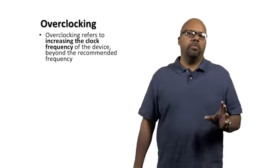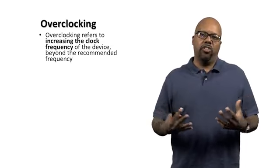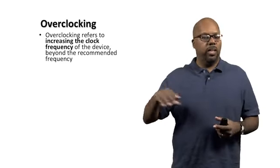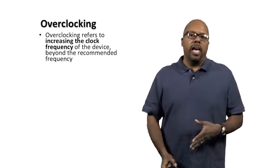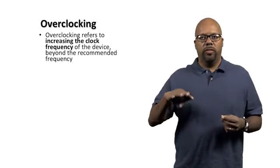Basically these processors, these machines, it's called synchronous design. So there are clocks, meaning square waves, up, down, just 0 volts, 5 volts, 0 volts, 3.3 or something like that, that are driving these chips. And the clock frequency is the rate at which the signal goes high or low.